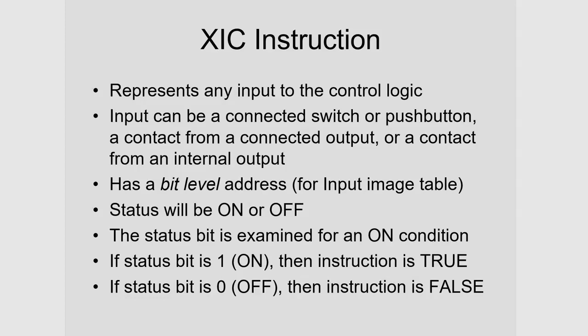That's contrary to other digital devices. I mentioned in previous videos that most other digital devices are byte oriented, not bit oriented. So the smallest level, let's say for your PC, if you have a PC or a desktop, the smallest piece of data that you can grab is a byte, whereas in the PLC we can actually manipulate an actual bit, a single 0 or 1. That's one major difference between the PLC and the normal PC.